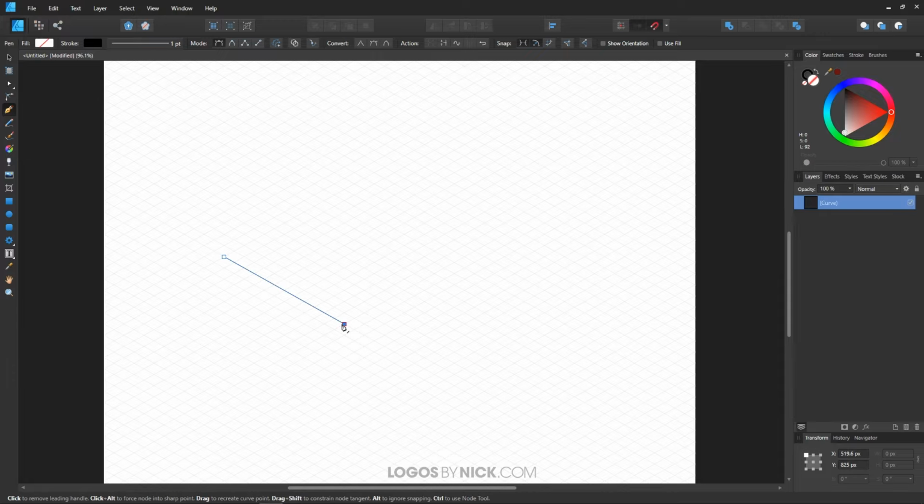I'm going to go ahead and click. Then I'm going to hold Shift again, bring this out this way. I want to make this the same distance going this way. I'm going to use 300 again. We don't have to actually count these boxes now that we know what the number measurement is. So I'm going to bring it out until it says 300. There we go. Now let me bring the line coming up this way.